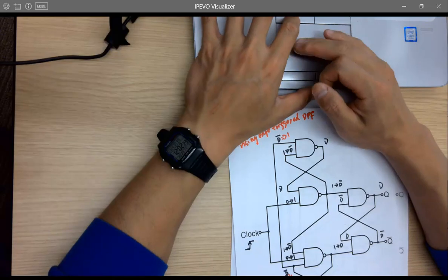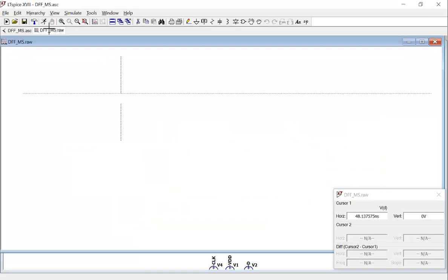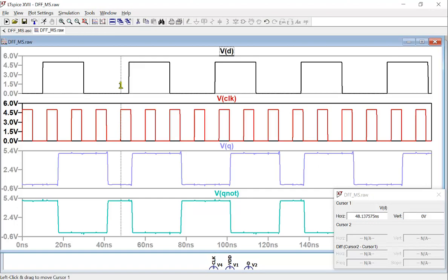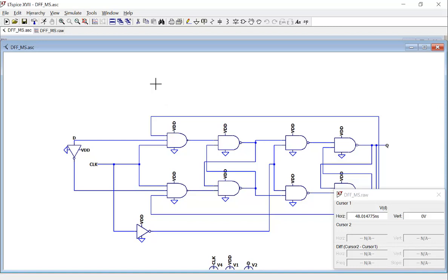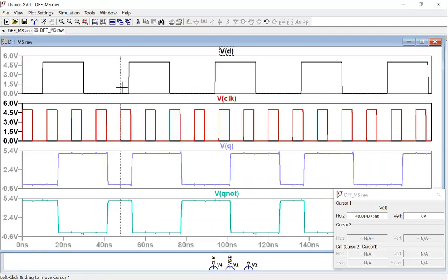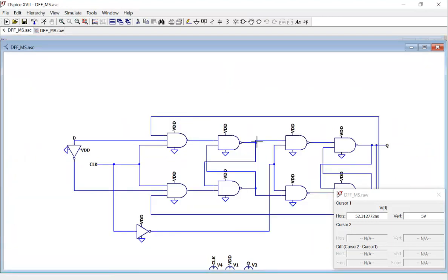That's why in the simulation, even though the rising edge here sampled a D to the middle pane here, right? However, the data changes during the clock's logic 1 time. See? If you look at the D on the top, after the rising edge, it changes from 0 to 1. So that change will be passed to the middle.